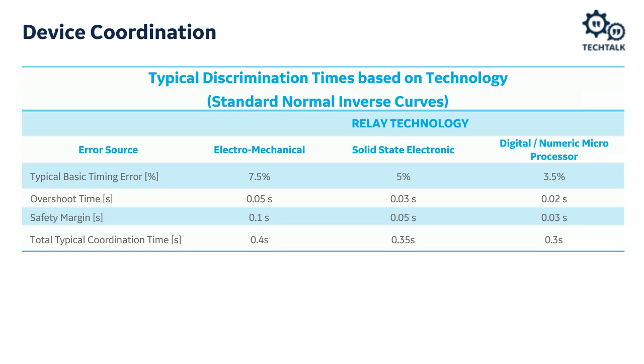Now, we don't have a disk that moves in a microprocessor-based relay, but remember I said earlier that the way we're going to calculate quantities is we're going to take samples of the waveforms that are attached to the relays and then use something like a Fourier transform to turn those sampled values into a magnitude that we could then run through a comparator to operate.